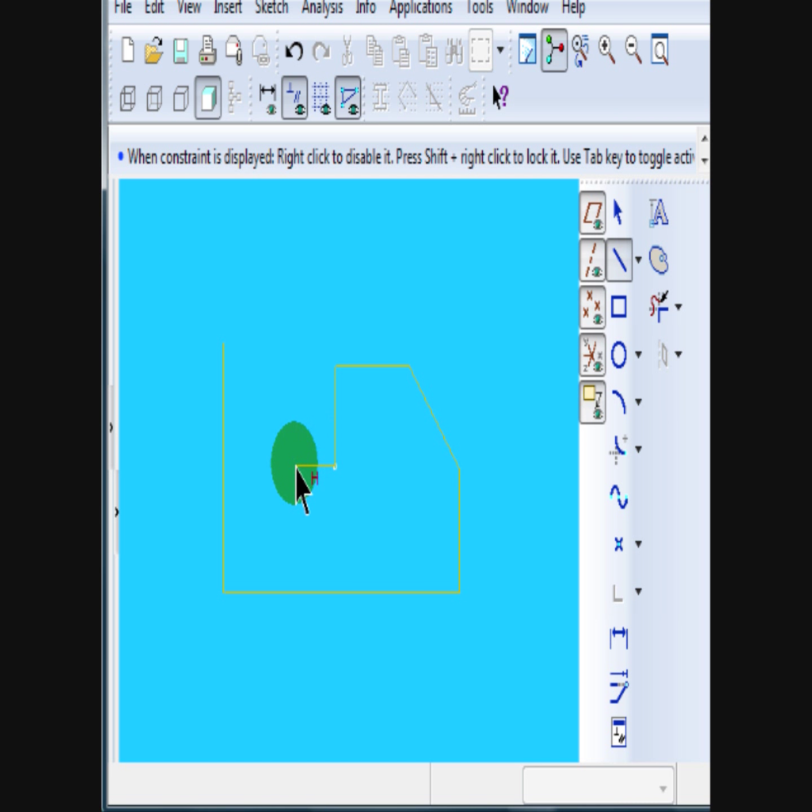Up to this point, you've been using one tool, which is the line. Now try to match them almost to the same level. Now, using the arc, click on the ends of the lines for the first 2 points using your left mouse button. Then stretch the arc outwards, and when you see that tangent constraint, that letter T in one of the ends, then click again.